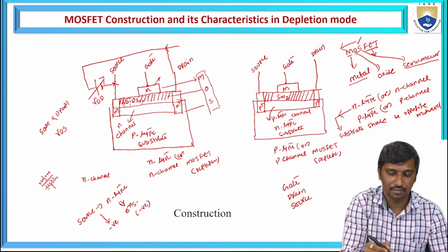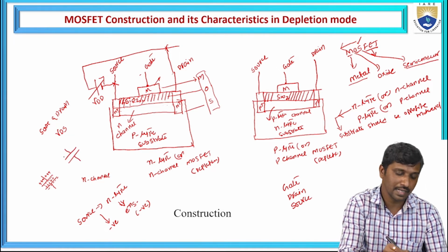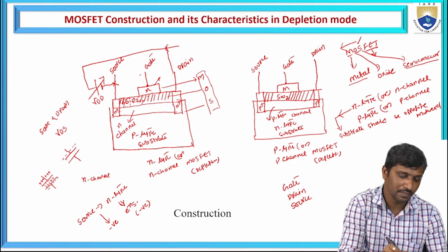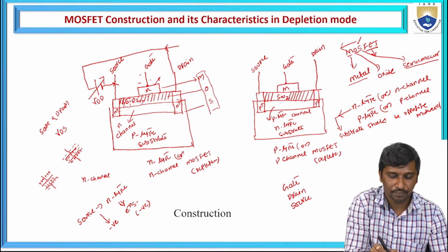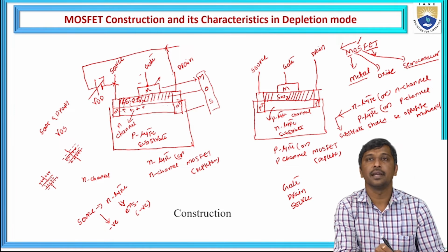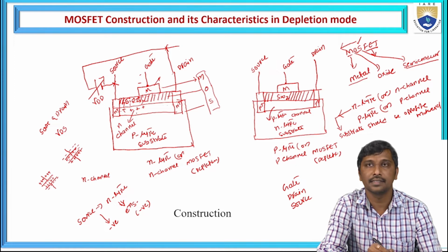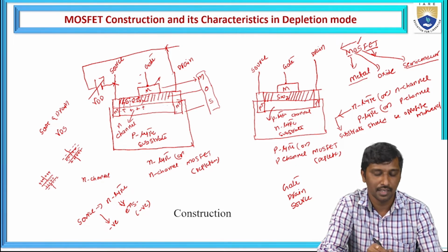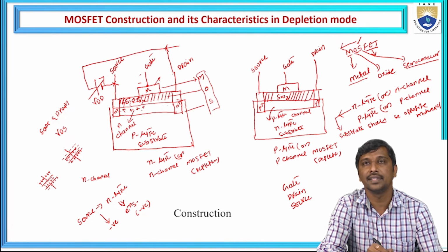the gate must be biased with a negative voltage. If you apply negative voltage to the gate, the plate next to it becomes positive, so a positive charge is established in the channel. It acts as immobile ions and occupies some of the width of the channel.